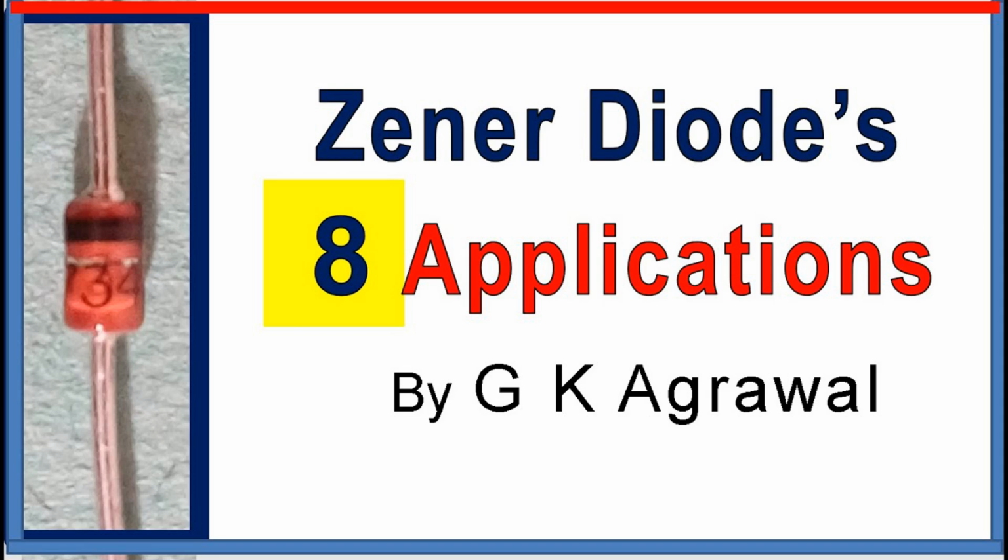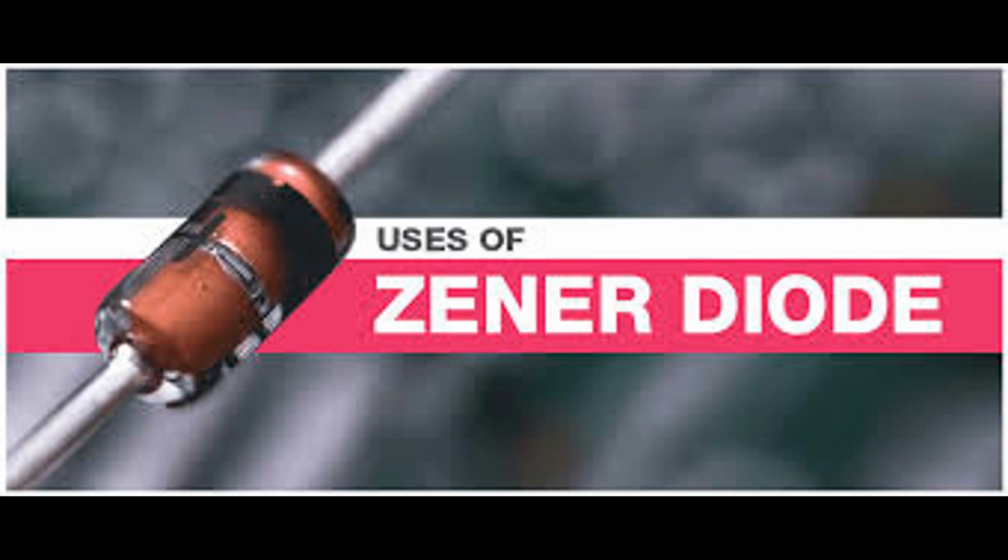Design considerations. Power dissipation. Ensure that the Zener diode operates within its power rating to avoid overheating and damage. Series resistor. Properly select the series resistor to limit the current through the Zener diode and achieve desired voltage regulation. Temperature effects. Consider the temperature coefficient of the Zener diode, especially for precision applications. Summary.